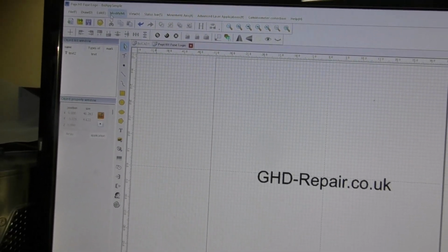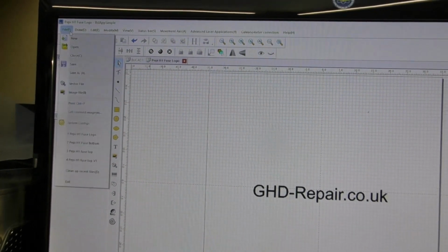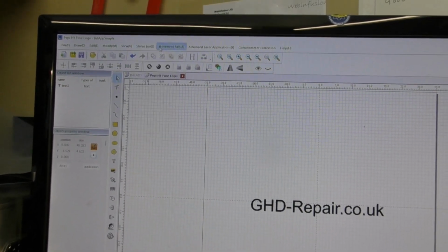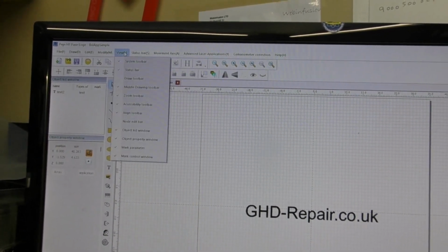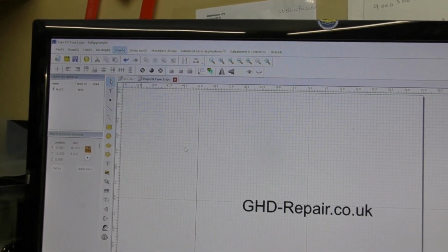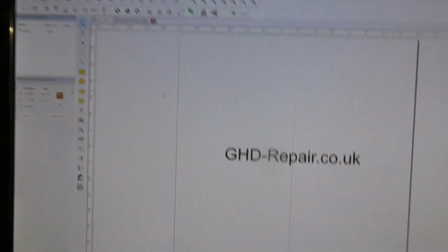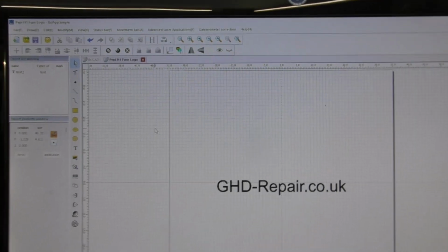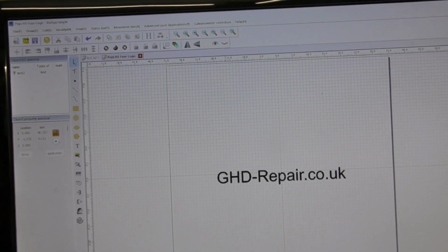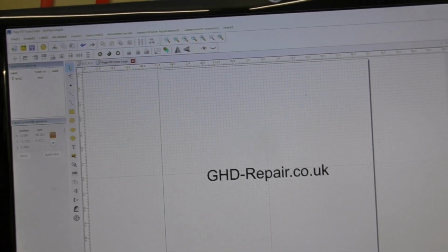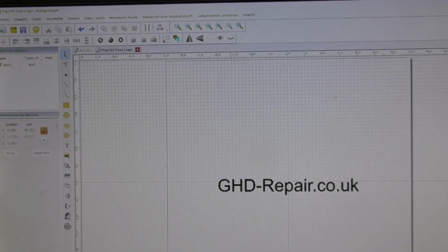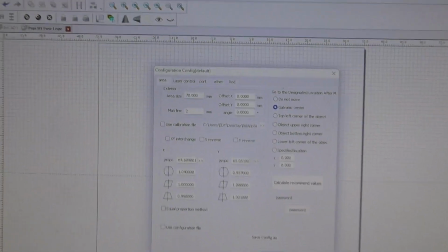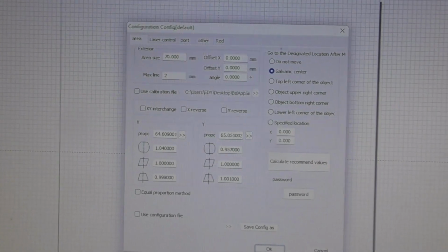So I've gone through all of these drop down menus looking for this calibration menu, and it just isn't there, but as I say, I came across it in the user manual that I looked at, and you basically press F3. So there we are, there's the F3